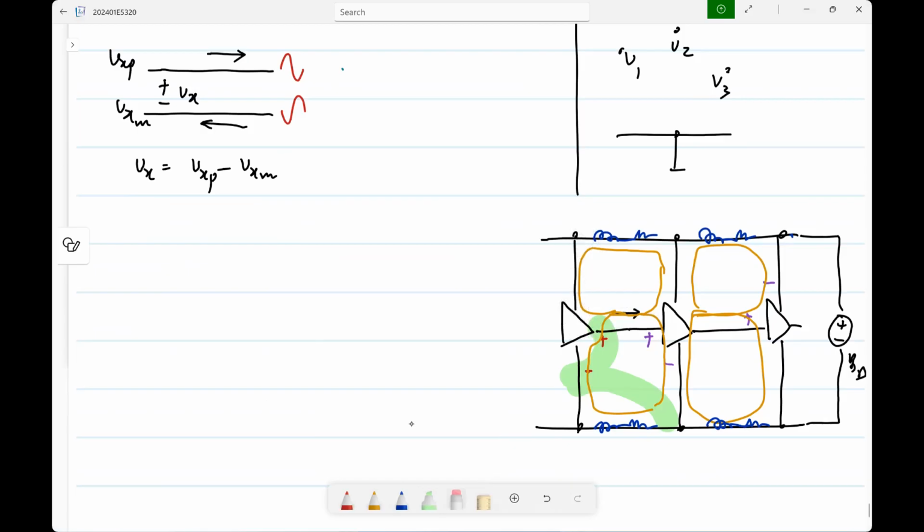That is one possibility. Another possibility is the current here is a sinusoid, the current in this rail is half of a sinusoid, that is halfway rectified. The current in the bottom rail could be the other half and so on. In fact, they are even non-linear. That is, while the actual intended voltage and currents don't have any harmonics, the currents drawn from the supply rails can have harmonics.